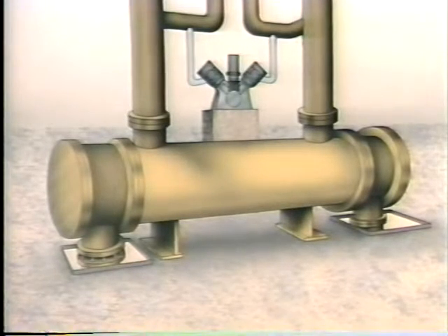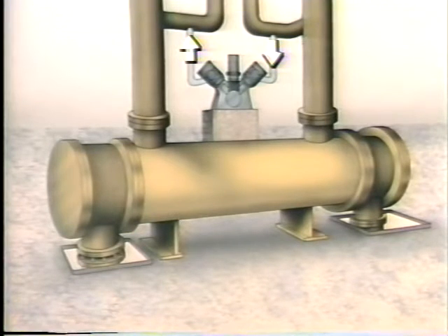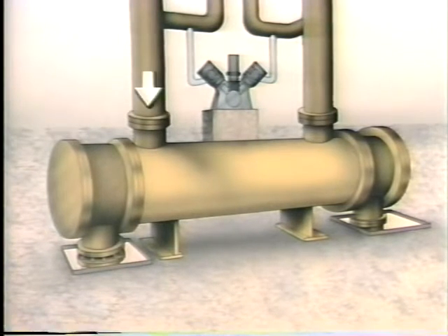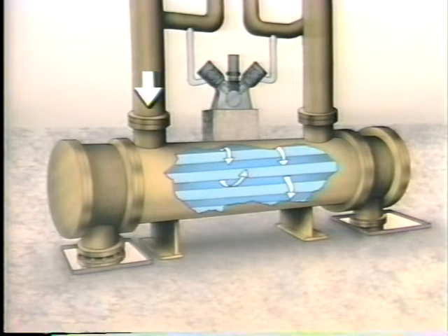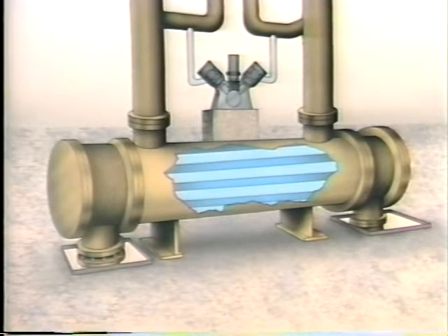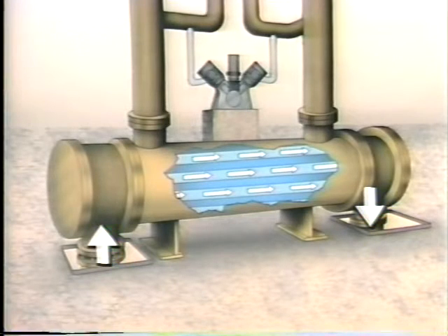In this system, cooling water is circulated through plant equipment in order to cool the equipment. As the cooling water cools the equipment, the water becomes heated. The heated cooling water flows to a heat exchanger and is circulated around a bundle of tubes inside the heat exchanger. Water from a river, called raw water, flows through the heat exchanger tubes and reduces the temperature of the cooling water that flows around the tubes.